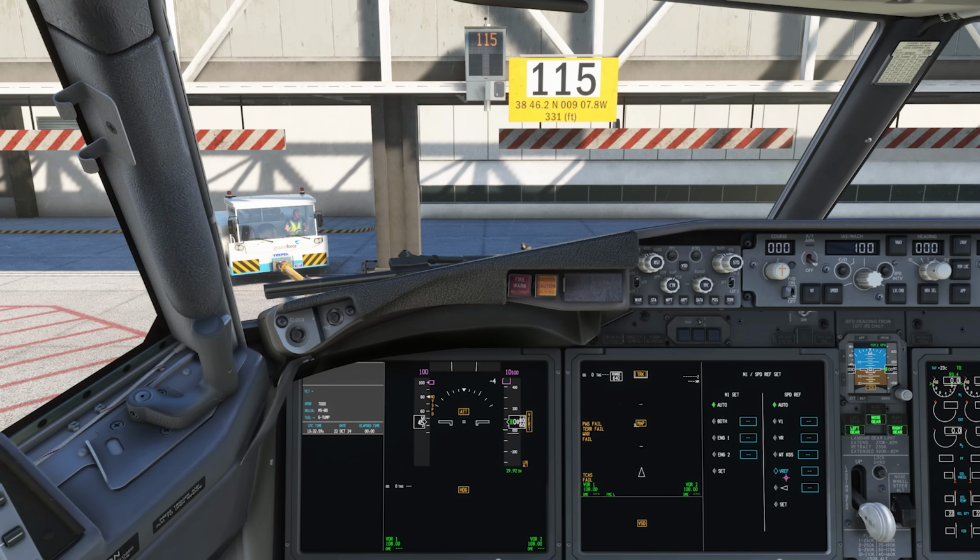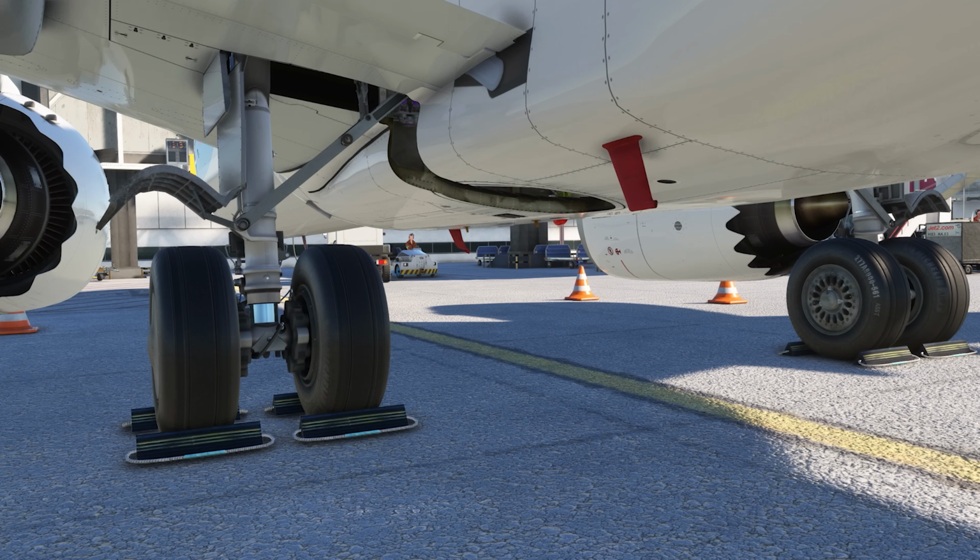In relation to the landing gear, we also have the wheel brakes. We just move outside here. All the MAXes, I believe, and certainly with our fleet, are fitted with carbon brakes. Again, in a desktop simulator, you're not going to really notice the differences here, but certainly in the real aircraft, when we're taxiing, it's quite hard to judge when the brakes bite, so it's quite sudden with the braking when you start braking lightly. But the brakes offer significant weight savings over the steel brakes, something around 300 to 400 kilos.